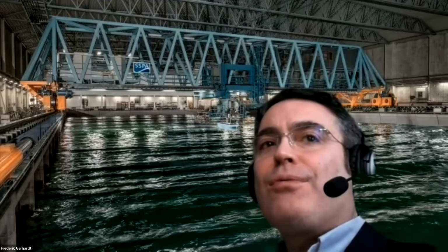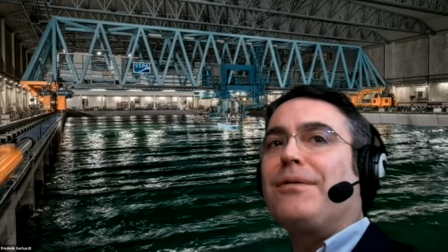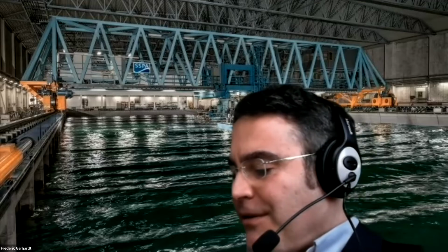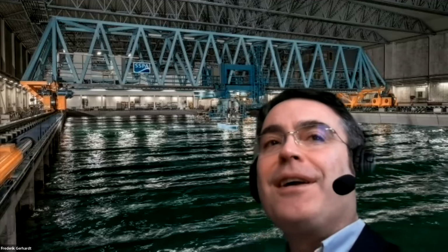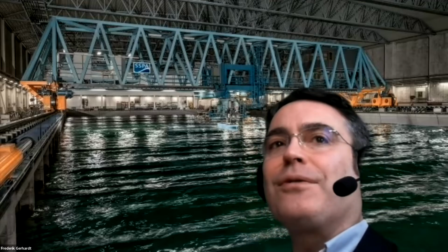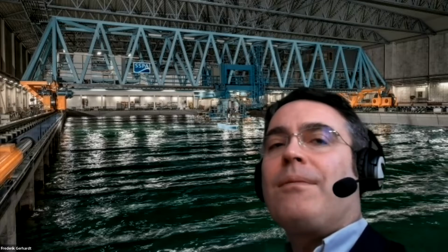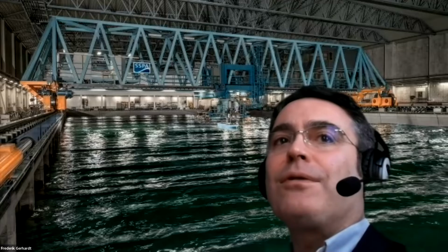Yes, at this stage, I wouldn't really call it a digital twin in the very strong definition of the word, because there might not be a physical ship yet. What you do to find this balance is a simulation approach. You look at those equations that Josh showed, and you try to find resistance curves for the ship, how much force is required to bring it up to a certain speed, and then you need to make the decision: where does this force come from? Do I want to have it from the main engine? Should it come from the sails? What really is my goal? Do I want a sail assisted ship which saves 10-20%, or do I want to go all the way to 90% fuel reduction?